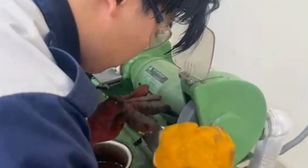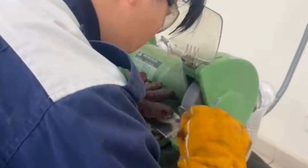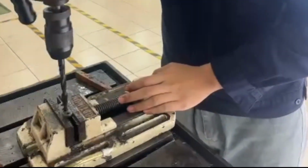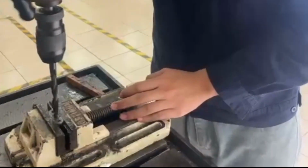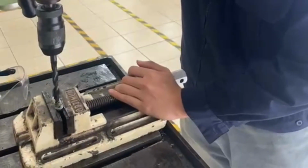After the face milling, the workpiece was finished using the pedestal grinding machine to further smooth the surface. Then, a larger drill was used to produce the countersink on the required hole, which is the middle hole. This allowed the screw head to sit flush with the surface.